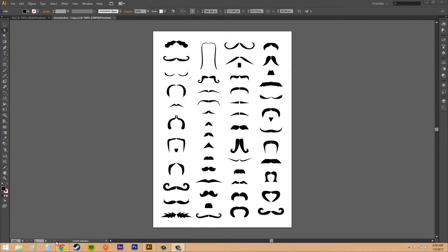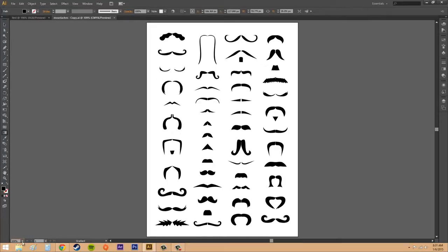Actually, we got down here, I forgot to go over this section here where it tells us what tool we have selected. So right now I have the direct selection tool. If I pick this one, we've got the selection tool, and I'll come down to here. Now we've got the gradient. We've got our zoom amount here. Fit on screen will pretty much help you out the most, I think. And then we've got here our artboards, and since we only have one, only one shows up. And you can use these panels here to switch between your artboards. As you can see, you can have more than one artboard in a document. That way you don't have to have a whole bunch of documents open. You can just go through each one. Kind of like if you ever used Excel, you have different workbooks, and in this one, you have different artboards.